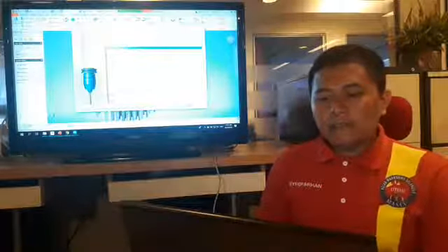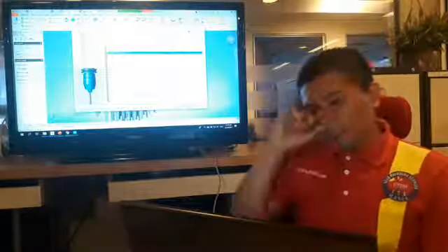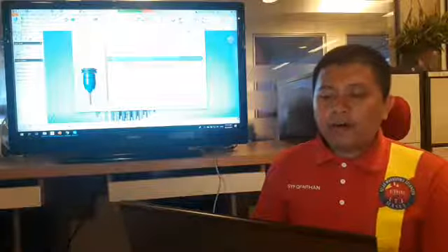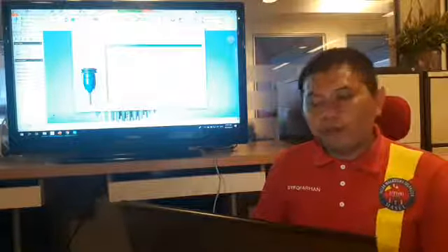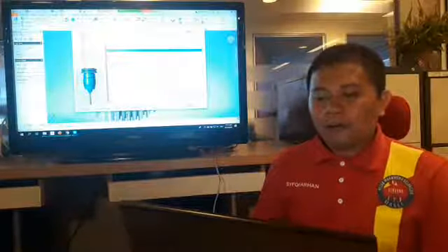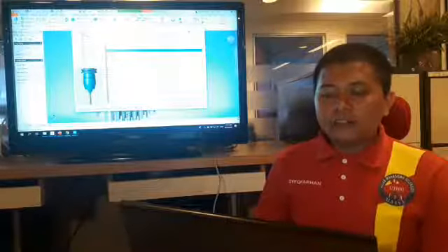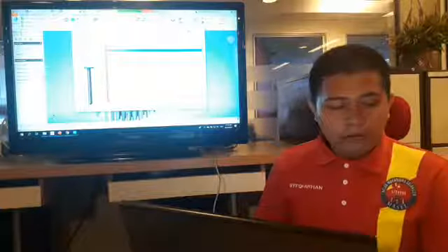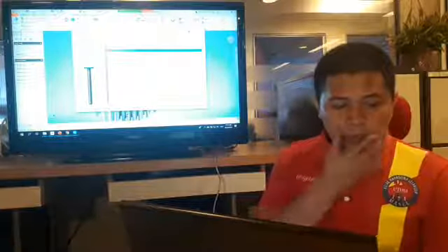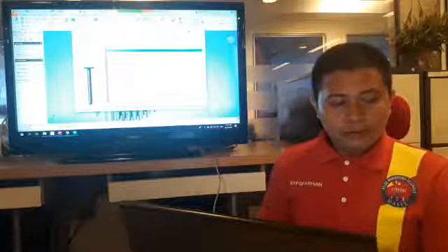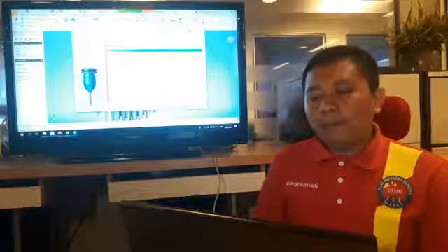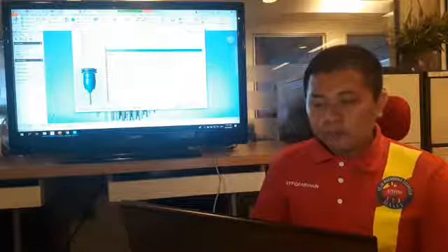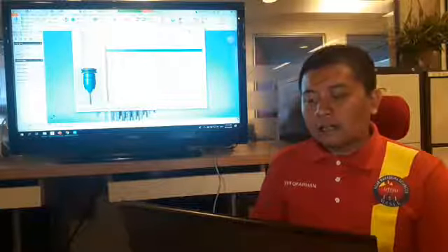So I can choose the 5 mm drill over here. As you can see, inside the Inventor CAM library, they already created a few tools for you. If you want to check the end or countersinks or anything, you can just simply mouse over the image over here, and then they will zoom it for you. So for example, this will be the correct tool for me. I just simply click on select.